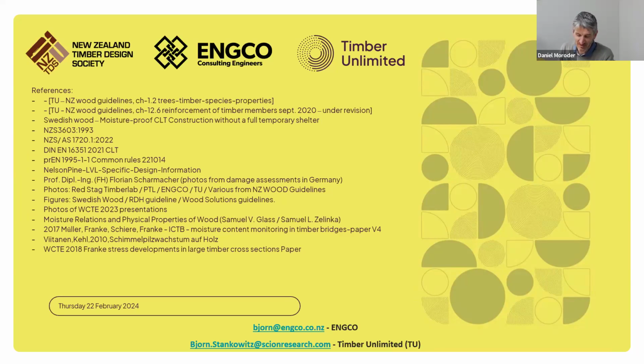Thank you. The thing I would like to add here is, I think engineers who are working with mass timber should have their own moisture meter, and contractors should have their own. Second, these moisture meters measure current, essentially how much the water can pass on the current between one probe tip and the other. If you treat your timber with chemicals, especially copper or boron, it transfers more current. So there are factors which you should apply depending on the treatment and the material. I understand that these values are normally available from suppliers, freely available on the web, and come with some of the moisture meters. Do you agree with my comments on that, Bjørn?